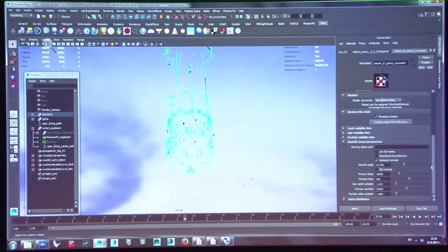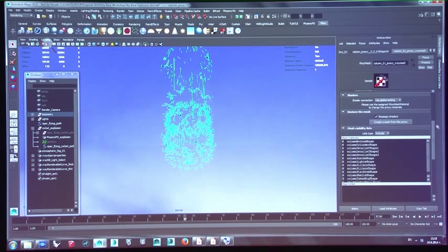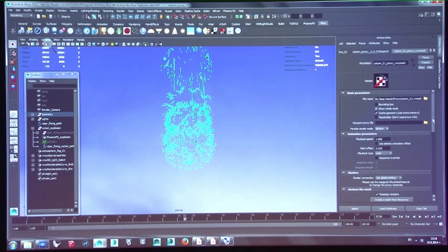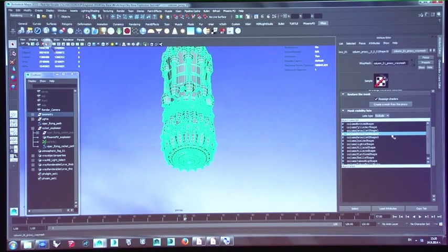A cool thing about the V-Ray proxy is actually that it allows you to save animated meshes if you want to. You can play them back at different speeds or loop the animation or whatever. And we have mesh visibility list, which actually allows you to turn on and off parts of the V-Ray proxy, which is really neat if you want to make variations. So, for example, you make, just an example, a neighborhood of houses, and you can switch on and off different houses in the neighborhood. Just a wild example here.